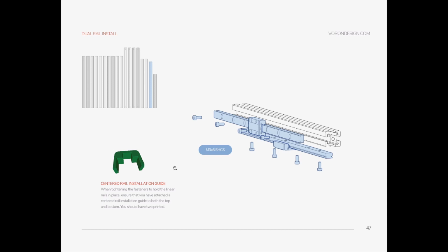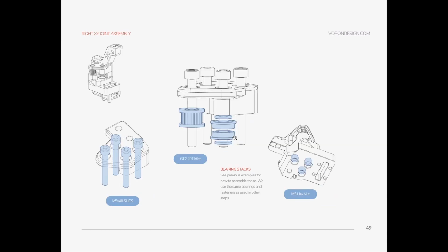I did it like that. But don't tighten the second one, because later on, once you install the afterburner, you will move your head and try to find the home position of your second rail. So one of them will be placed rigid, the other one just take the empty part. Don't tighten them yet.